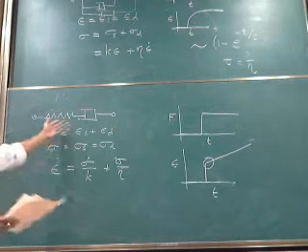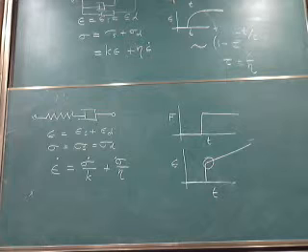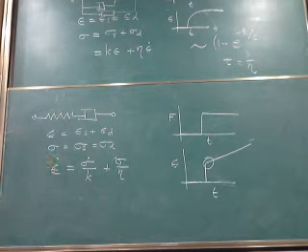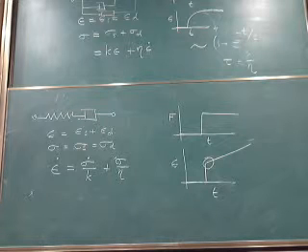So what kind of material shows this? This can be seen in polymer solutions, and polymer solutions are a little bit more complicated than that, but they are viscoelastic liquids. And I have a sample material here which I'll pass around. This is some kind of putty which I bought from a toy shop. If I roll it into a ball and throw it, it bounces. So you will say this is an elastic object.